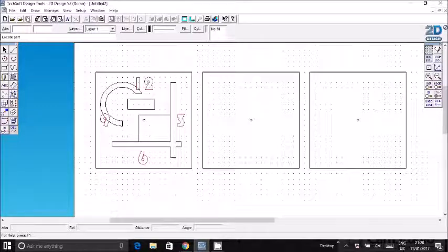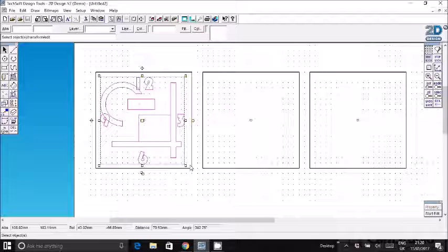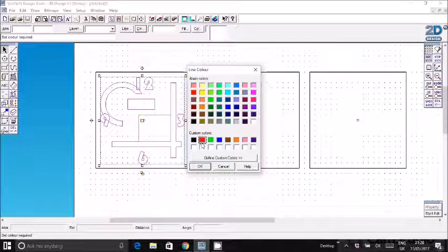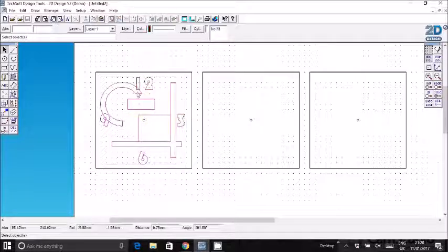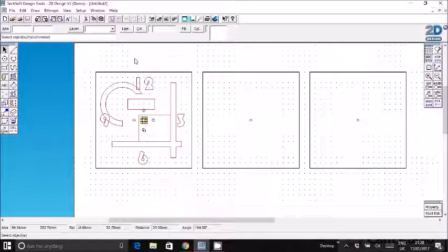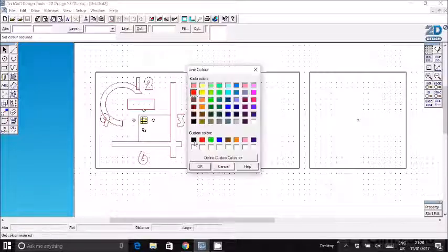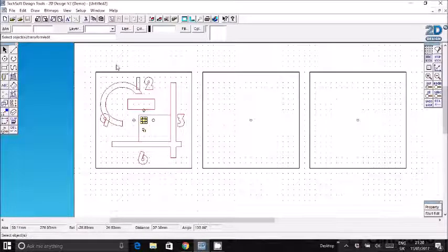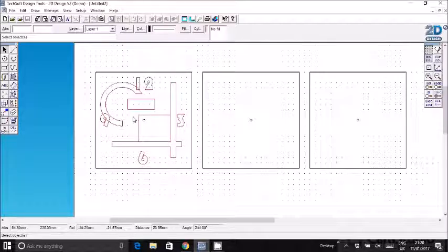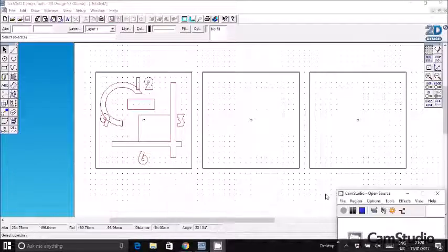So you would click save here, and the last thing I'm going to do is just select everything and make sure the line color is red. Click that. So everything inside it is red apart from this center circle, which is going to be black, and the reason is it's going to laser cut everything in black, and it's going to just engrave, very lightly cut everything in red. So there's the first one, that's Bauhaus. Save that and see if you can complete it. Okay, have a go.